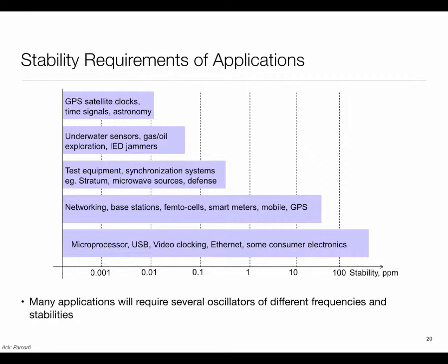So it's very hard to synchronize a sensor which is deep down in the water, even if it could communicate with some device on the surface accurately, because you have a communication link which is long latency and very delay prone. So the way to deal with this is that you compensate by having much more accurate clocks. By the time you start hitting these, you are looking at stabilities which are now a fraction of a ppm.